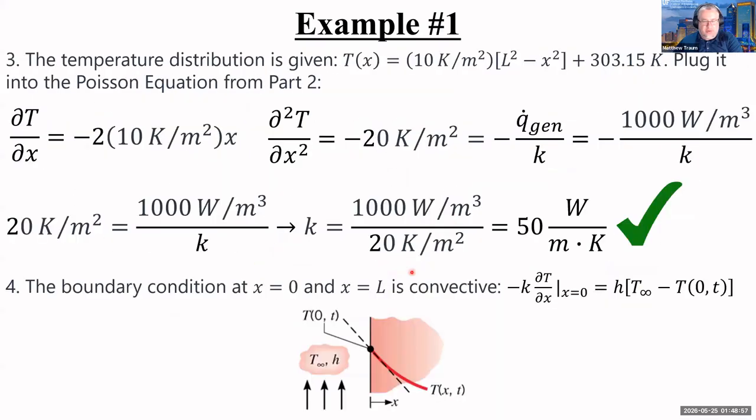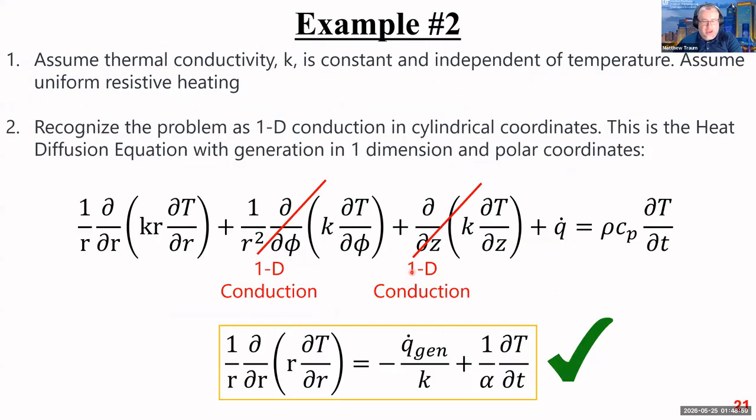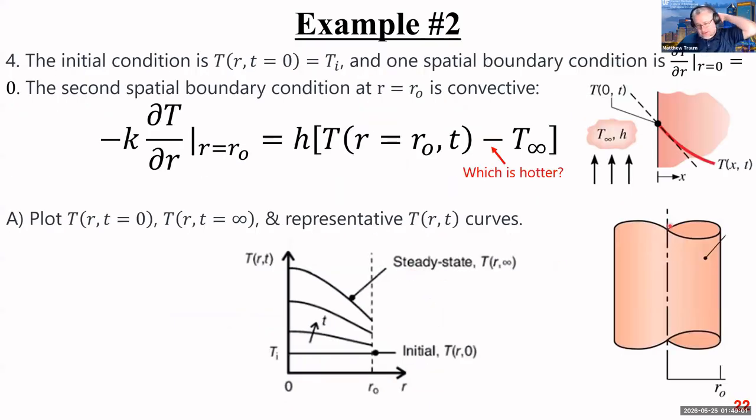So the same is true, even though we don't have a temperature profile drawn yet. The same thing is true here. This is a center line, and the geometry is axisymmetric, and so at r equals 0 at that center line, the derivative of temperature must be 0. And that makes sense from a conduction standpoint too, because you don't have any conduction in the r direction right at the middle.